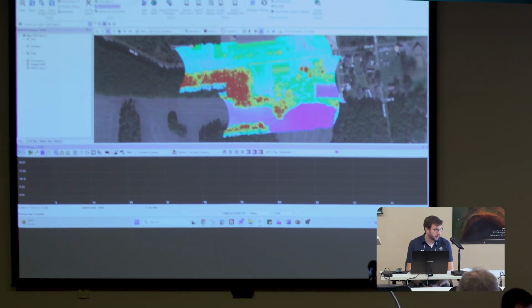the first thing we're going to do, and we've done this the last couple of days, is just export a DEM with breakline enforcement. So let's just glance at the data real quick and make sure it looks okay. Since this is a DEM that I'm producing, at the top here we want to look at how the surface looks.